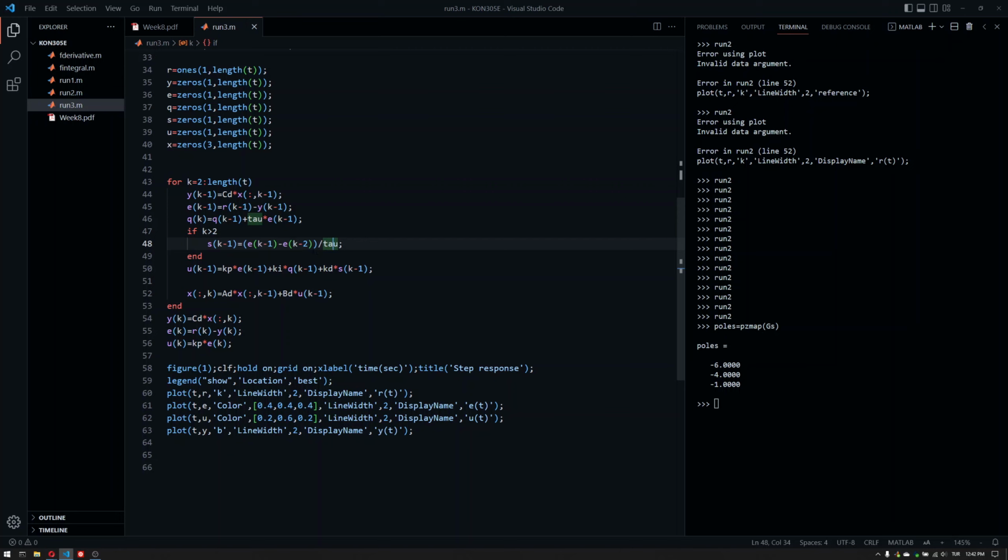Now, let's see. We start off with a PI controller for one sample. And the first sample is also not really important because that's the initial step. So 2 samples of waiting in order to get the derivative going. But that's exactly the shift, and looking back to the history of the system instead of looking for prediction is the portion that is going to be like a derivative. So it's a delayed derivative, sort of. Let me check twice here. Yeah, that should be it.